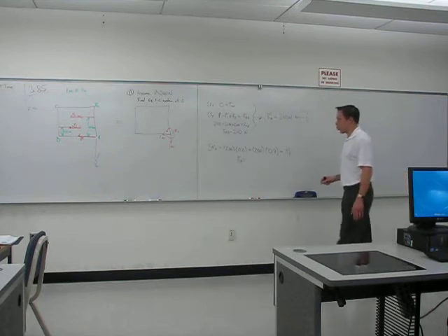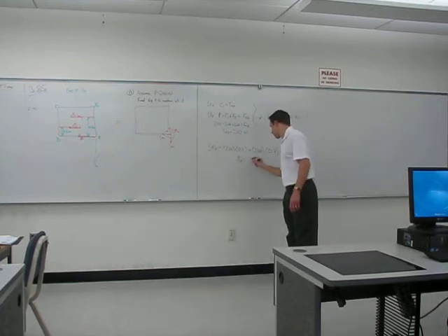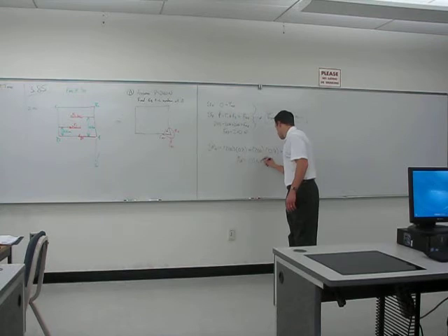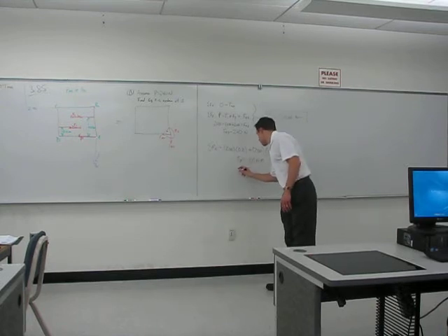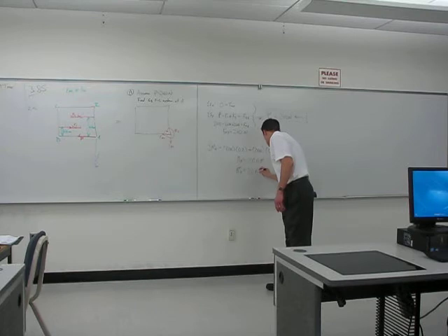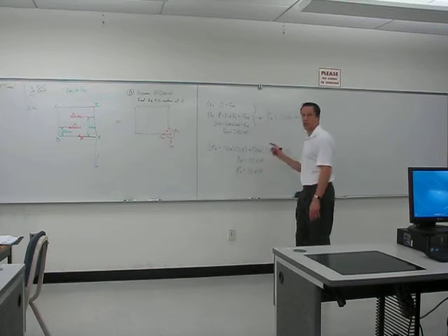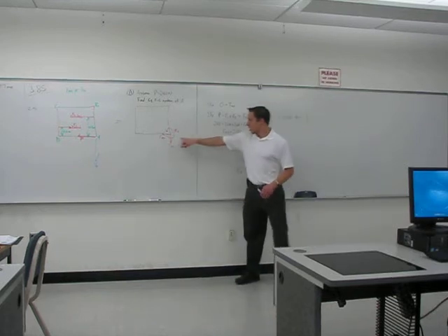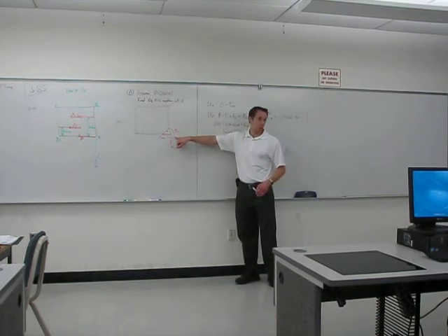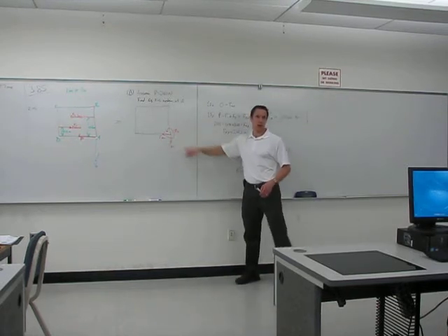Looks like we're going to get 100 if we do that, Newton meters. Now remember, moments are vectors, so we need to say here that the moment around A, positive 100 means the direction of rotation ends up being counterclockwise. Or more correctly, we should say it's consistent with what we assumed in this picture, and I assumed counterclockwise.